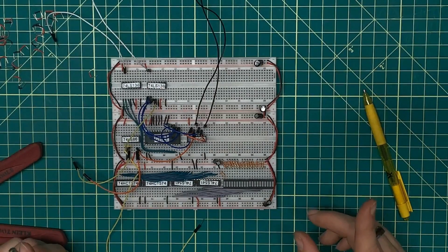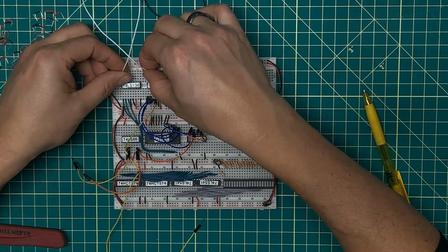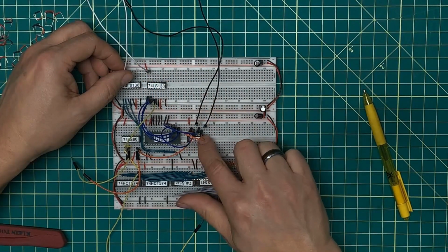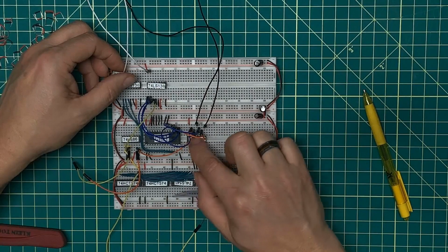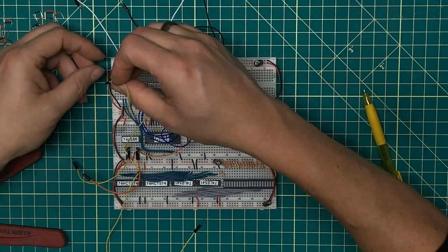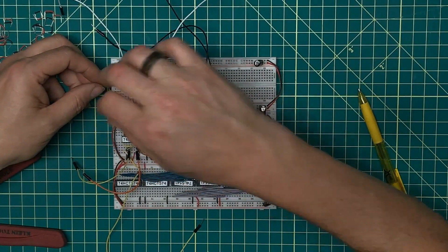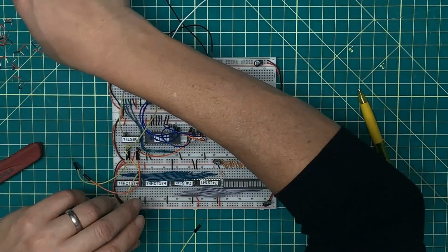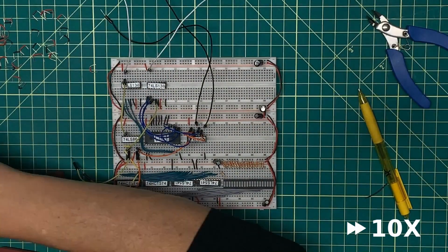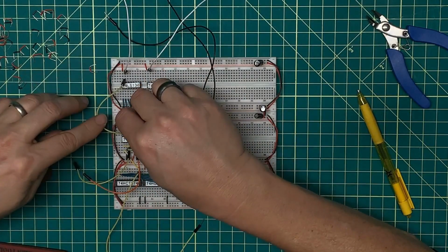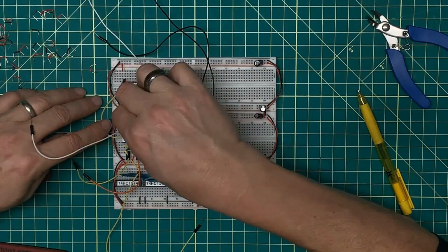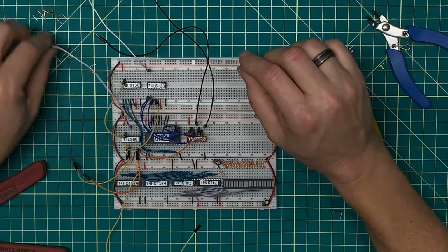Now, we're not quite done yet because these two signals also need to be buffered. Because I don't have anything that is ANDing these together or any other condition that needs to take place, I need to run these through a buffer. So real quick, I'm going to take this output, put it into the LS86, which is then going to make some more wires here real quick. This needs to be buffered, so I'm going to take the other side of that low, and then this becomes the output. And again, this is the address bus 1 assert.